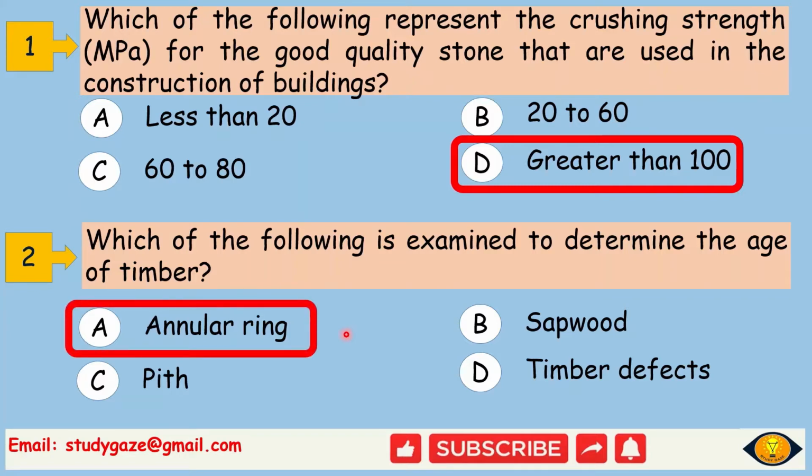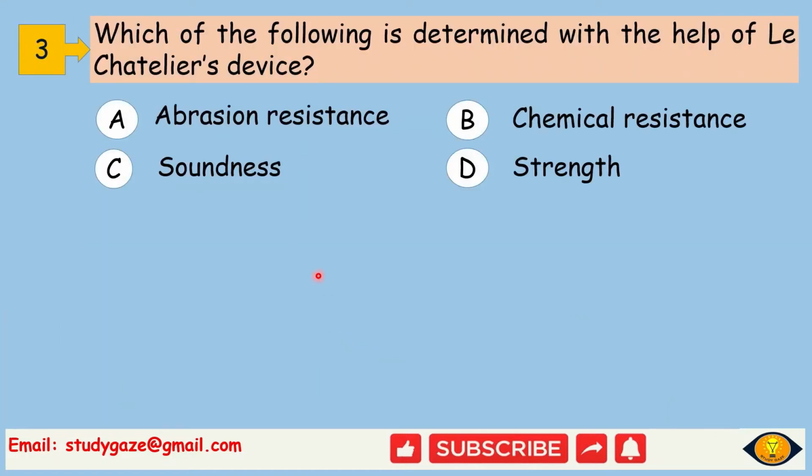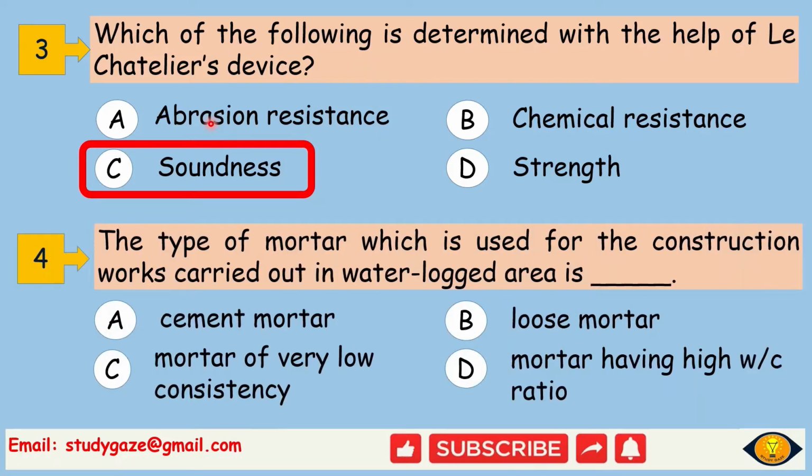Next, which of the following is determined with the help of Le Chatelier's device? So, with the help of Le Chatelier device, we generally determine the soundness of the cement. Next, the type of mortar which is used for the construction works carried out in waterlogged area is? The answer is cement mortar. We use cement mortar for the waterlogged area.